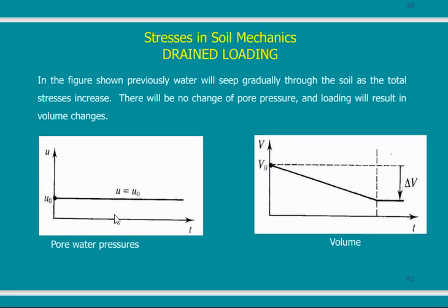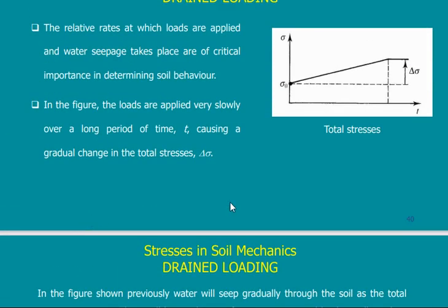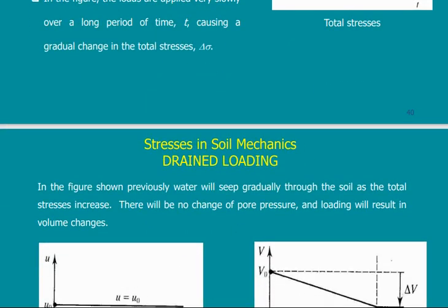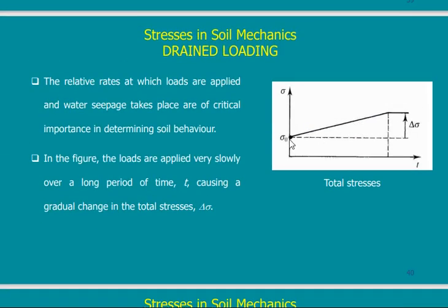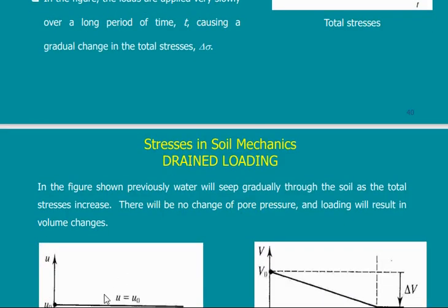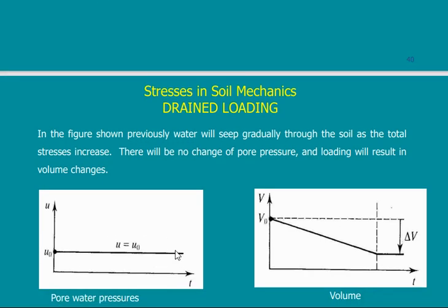Here, another two charts. Both are with time, but here it is the pore water pressure. If I start here with pore water pressure with a certain value, I will end up with the same pore water pressure because nothing happens. Water can easily leave and can easily go. If it was there before loading, then it will stay the same after loading. So water has no effect.